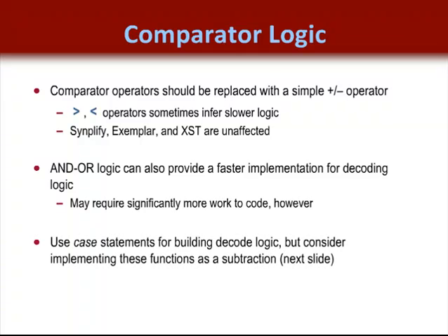Finally, always use a case statement when decoding logic. This tends to synthesize to more of a parallel implementation, or parallel logic as we call it, and tends to run at a higher speed. But keep in mind that even if the logic is built in parallel, a carry logic implementation should be faster.